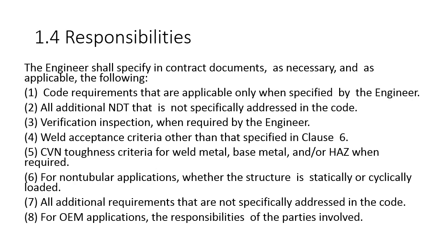They're also going to tell you whether there's toughness criteria involved. Impact properties. Carbon steel isn't going to react the same in, let's say Midland, Texas, where it never gets down to minus 45 degrees, or if you've got something up in northern Alberta in the tar sands where it's just ungodly cold for 5 months. And regular carbon steel will break like glass at 50 below. So they're the ones that make these decisions.